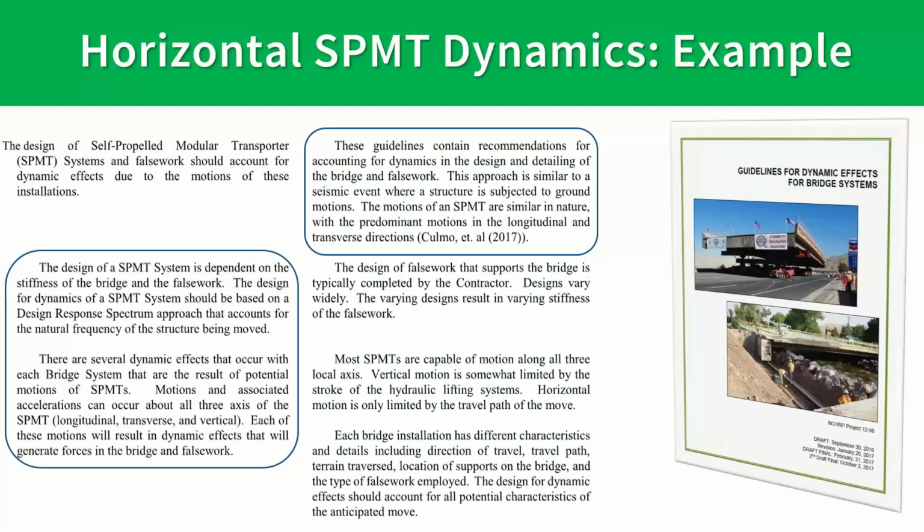The header on the top of this slide is green, which means we are referring to a guideline developed under NCHRP Project 12-98. This guideline is used to calculate dynamic forces on bridge systems using SPMTs. This is included in your handouts, so you can include that in your ABC library. The key thing is that the forces acting on the SPMTs and the bridge during the move are a dynamic event, similar to an earthquake. We have starting and stopping, accelerations and decelerations.